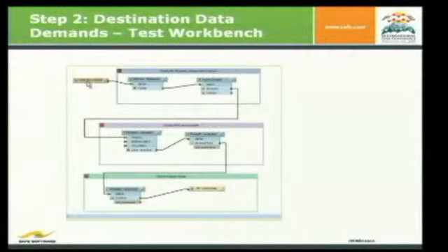We have the text file in here, and we do the 3D point replacing, and we do the raster digital elevation model generator here, and we do some other stuff here to get it right. This is easy to throw together, but the tricky thing here is getting these settings right. And this is one important thing to think of. When you work in the workbench, it's easy to throw these transformers in, but what does it mean if I use